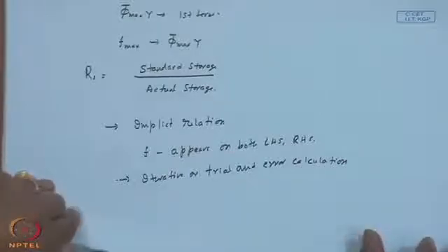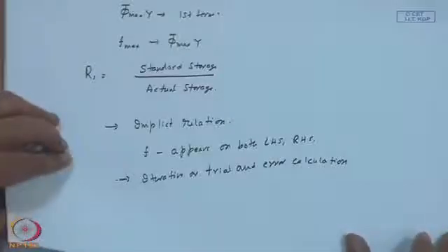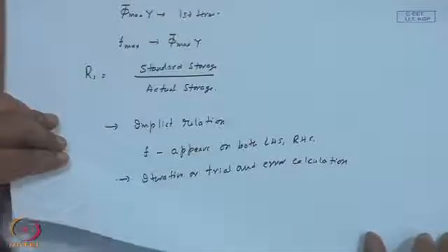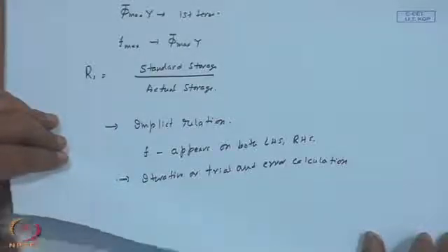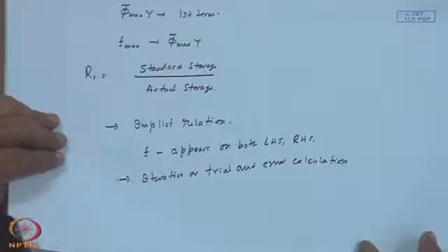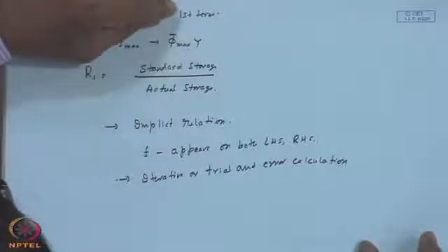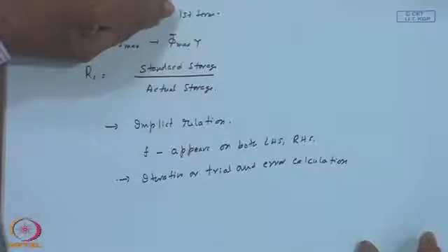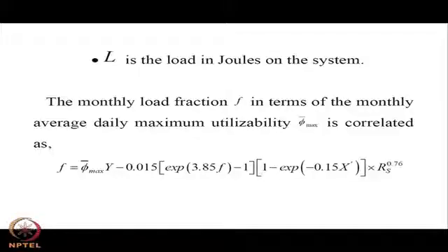So, compared to F chart, in addition to it taking into account the minimum temperature at which energy delivery is desired, we need to calculate the yet not known to us monthly average daily utilizability. Appears to be an exciting parameter, which comprises of the statistics of the solar radiation and the collector parameters and the operating condition at which the energy delivery is desired.